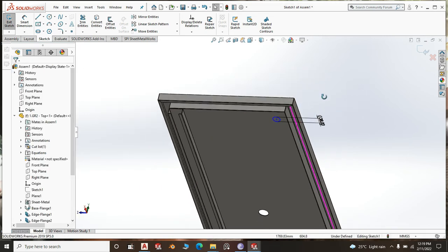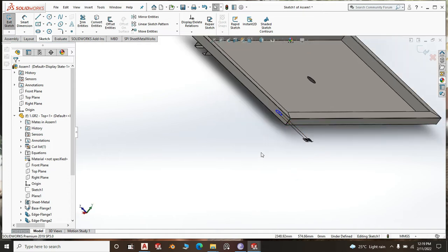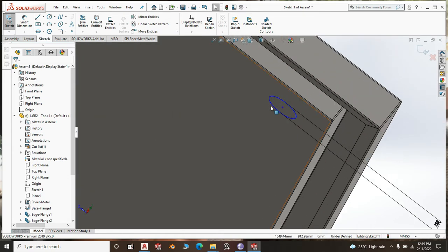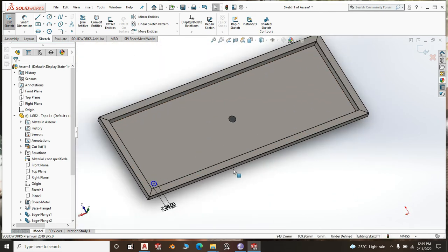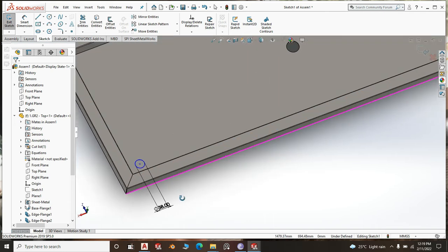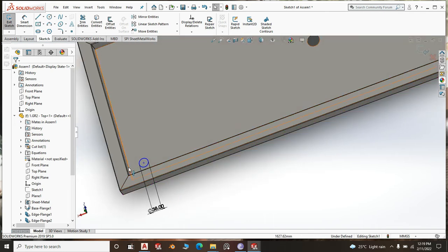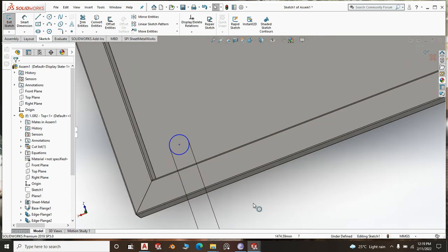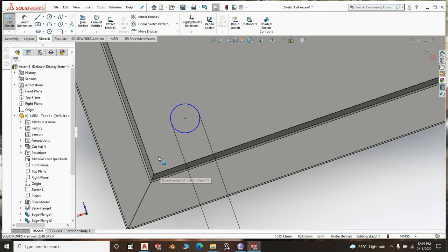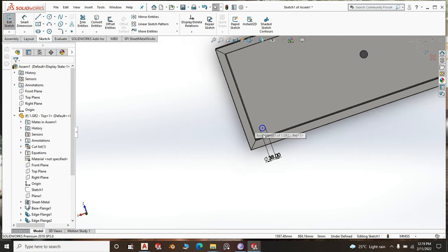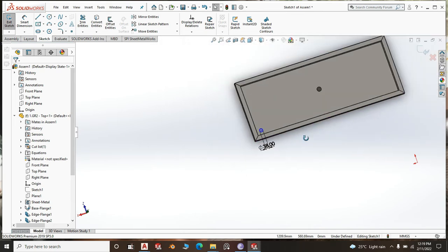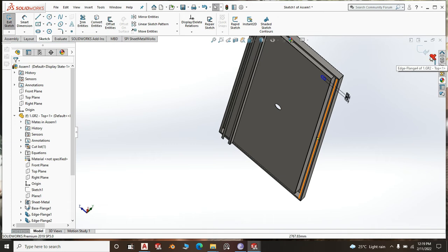Tentatively, let the leg be there. Now, if you're doing the welding on the top right here, the welding will penetrate to the top, and you see the leg should be right here at this edge, and polishing here will be really hectic. You will put tool marks all around this face, and you don't want to have an ugly table, right?